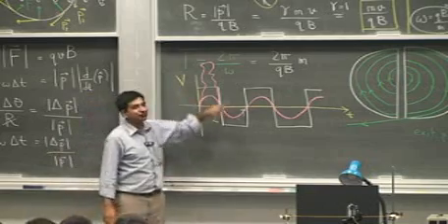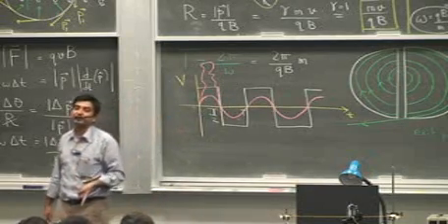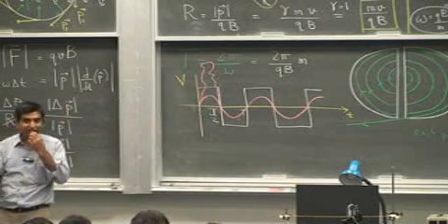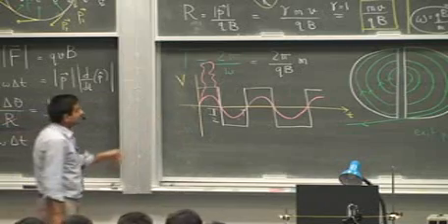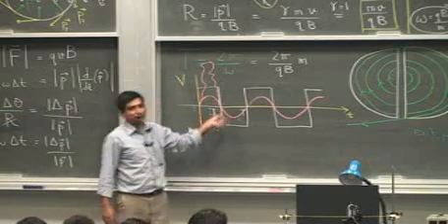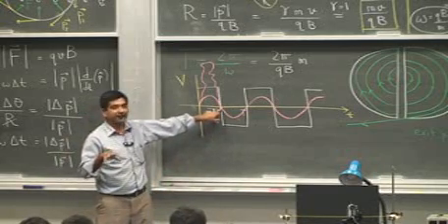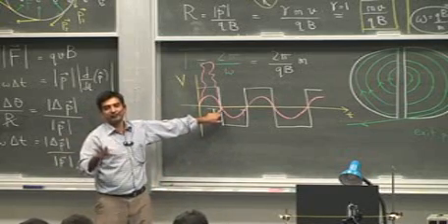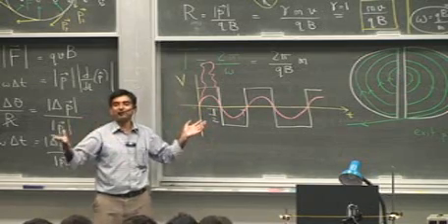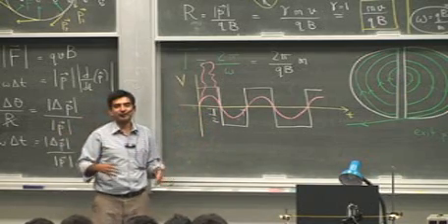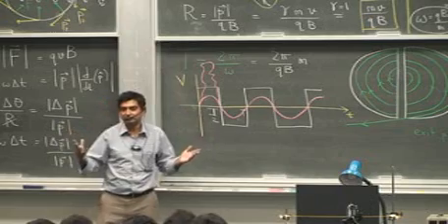So it's much easier to apply sinusoidal voltages in practice in technological applications because the variation is smoother. A square wave is always discontinuous at the edges. So there can never be a perfect square wave, and if you have large voltages and you're switching between large voltages, there will be lots of sparking.